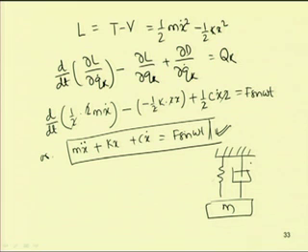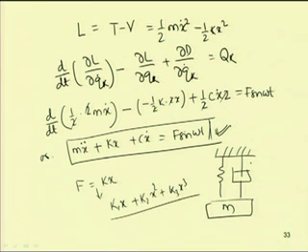The spring force, which was previously F equal to kx, can be replaced by k1 x plus k2 x square plus k3 x cube, or by using other nonlinear terms. By using the extended Hamilton principle or the Lagrange principle, taking the spring force equal to this, one can derive the equation of motion, which can be of this form.